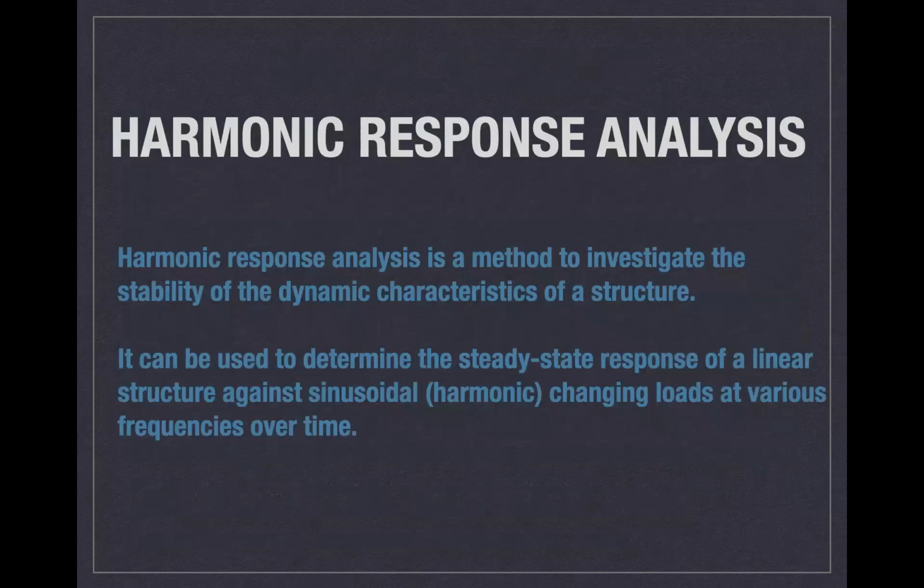The harmonic response analysis is a method to investigate the stability of a dynamic characteristic of a structure. It can be used to study the steady state response of a linear structure against harmonically changing loads at various frequencies, like some kind of wind, earthquake, or some other kind of force.